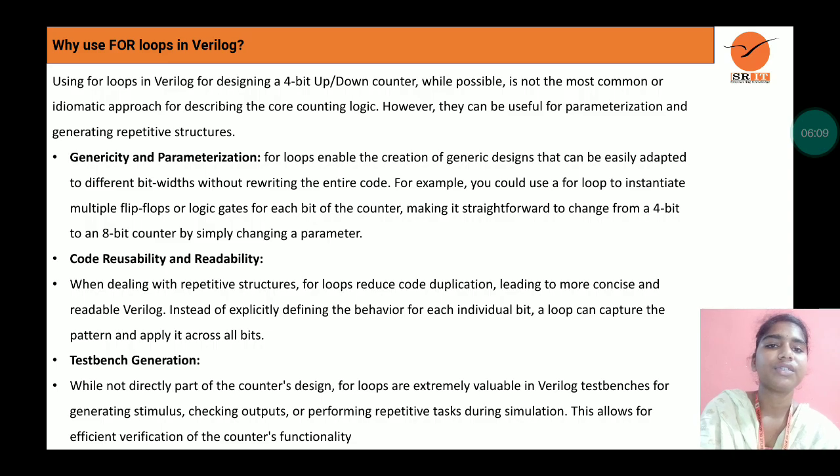Test bench generation: while not directly part of the counter's design, for loops are extremely valuable in Verilog test benches for generating stimulus, checking outputs, or performing repetitive tasks during simulation.